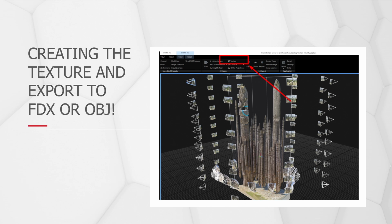Okay, so what do we have to do to create the texture? Are there any steps for that? Yeah. Again, Reality Capture makes this really easy. You go ahead and press the next step, which is create the texture. It'll probably take a few minutes. It is computationally heavy on the CPU at first, then goes into the GPU. Once you've created a texture layer, you can enable what's called the suite view in Reality Capture, which will show the mesh and the texture layer.